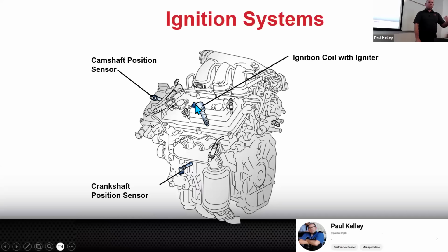At that point, we're looking at the diagram. We're seeing what voltage it should have, what signal it should be getting from the ECM, right? And then we're like, hey, it doesn't have voltage. And then we would just trace the wiring diagram down and find out why it doesn't have voltage. Maybe it got chewed. Maybe the ECM transistor is not giving the signal for the ground, right? So we'll come to that a little bit towards the end, because we do talk about testing the primary side, but this is what you're mostly working on.